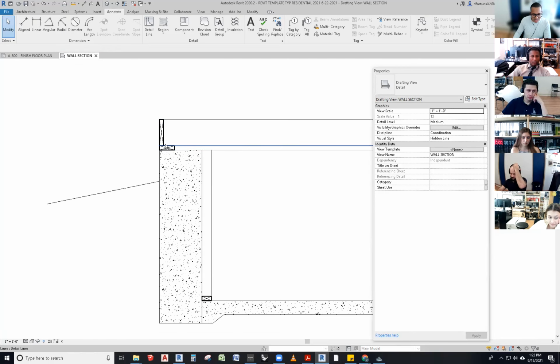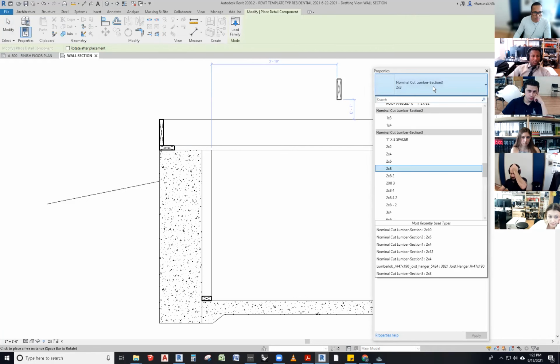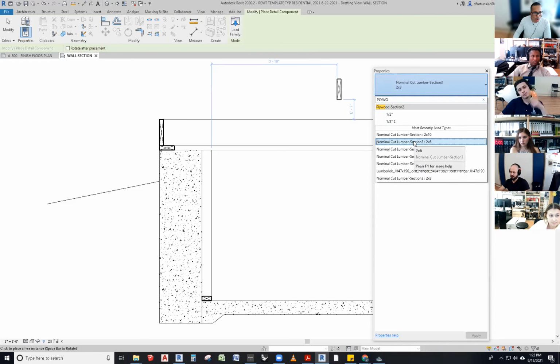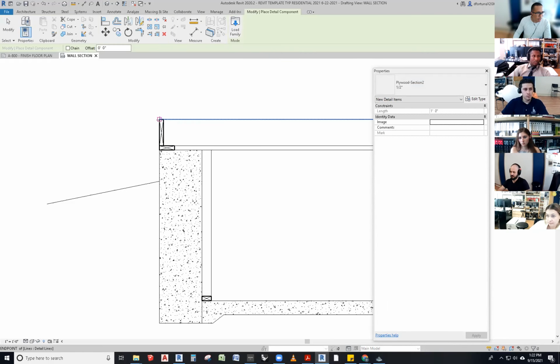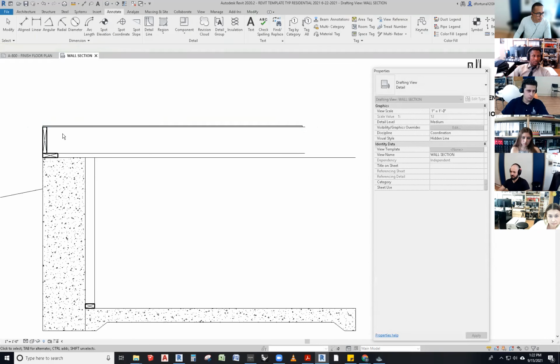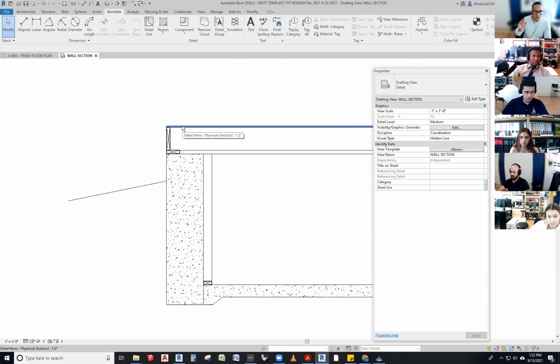Then the next thing that goes in here is plywood or some sort of subfloor. I don't care what you put, it's a subfloor. This is called platform framing. So it might be plywood. Clients have been requesting that we use 1/2 inch. I've been using 3/4 because it's pretty sturdy, but that sits right on top of these and it's going in the other direction. All right.